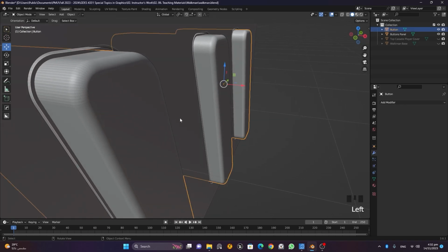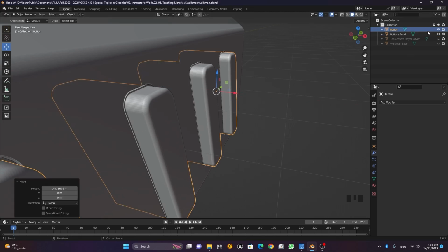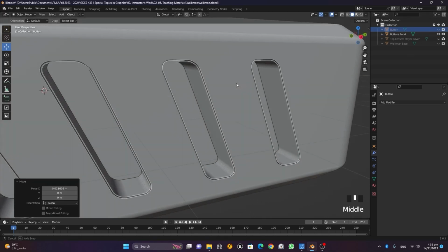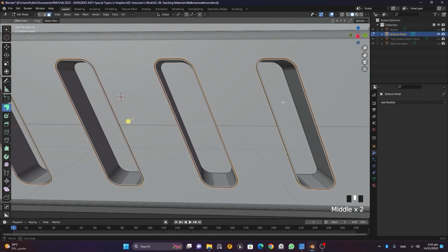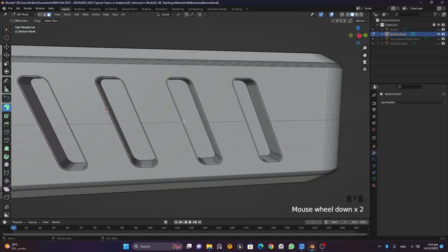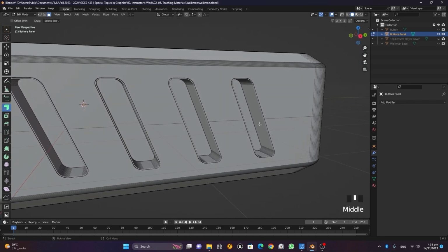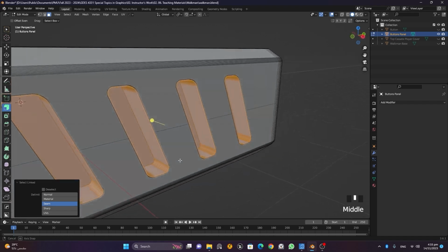So I can pull this. One more thing we can do here is optional. If you select this, press tab. Then if you press L on your keyboard and hover over these Boolean parts, they will be selected. Suppose I hover here, press L, over here L, over here L, over here L, and then they will be selected.